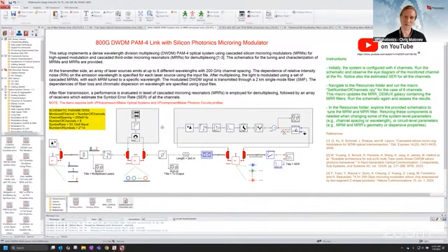So if you just take a quick walk through the schematic, you can see there are multiple laser channels, so different wavelengths, 8 different wavelengths in this case. We use this red GUI interface to represent an array of lasers. There's an array of silicon photonic microring modulators as well, connected in series. You have your fiber, a demultiplexer over here based on ring filters, so photonic integrated circuit components, and then an array of receivers as well.